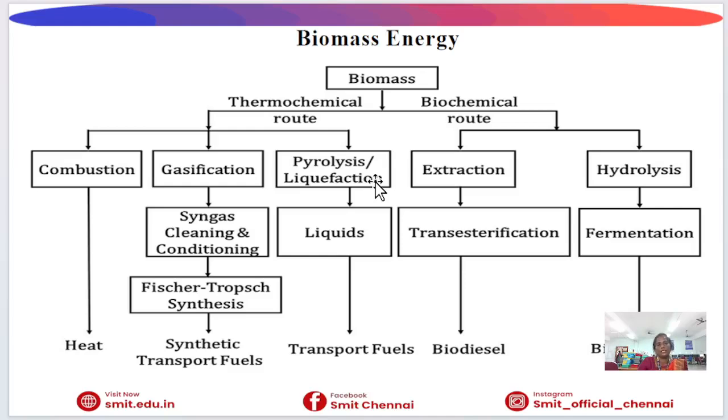This syngas can be converted into synthetic liquid fuels. Third one is pyrolysis. The biomass is heated without oxygen to form bio-oil, which is upgraded and used as transport fuel. Thus, thermochemical methods convert biomass into heat, gaseous fuels, and liquid fuels depending on the process used.